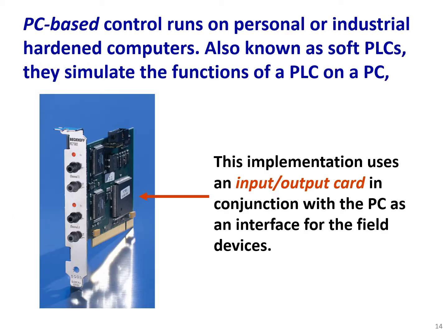PC-based control runs on personal or industrial hardened computers, also known as soft PLCs. They simulate the functions of a PLC on a PC. Yeah, so we could basically simulate a PLC on a PC by having some specific input-output cards, like this one.